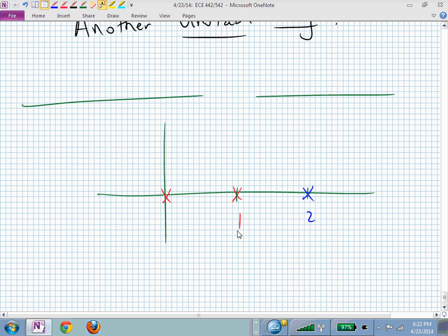And what are we trying to do with those zeros? Come here, come here. We're trying to pull those poles into the unit circle, aren't we? Here, little boy. Or whatever it is, some kind of an animal. Right? Come here. So we're trying to put something there in the z-plane to attract those poles inside the unit circle.